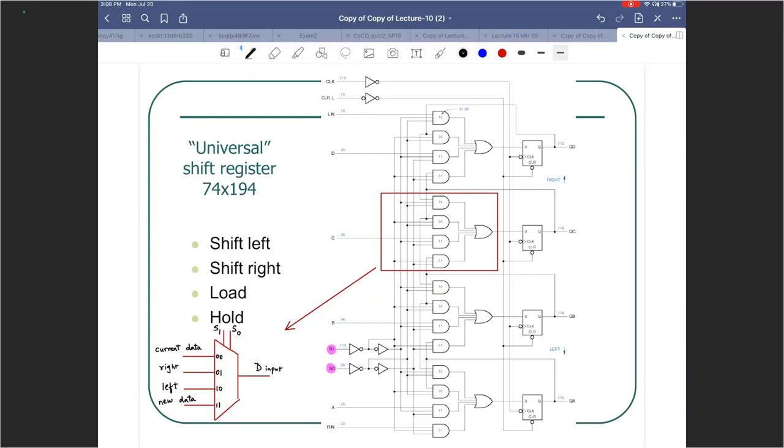There is a clock input, use an inverter, and feed it into negative edge triggered D flip-flops, making the entire design positive edge triggered. There's an active low clear buffer for fan out purposes connected to the active low clear on each of the 4 D flip-flops. So you can use this to asynchronously clear all the D flip-flops. So you can make QD, QC, QB, QA all go to 0 at once the moment you connect clear_L to low.